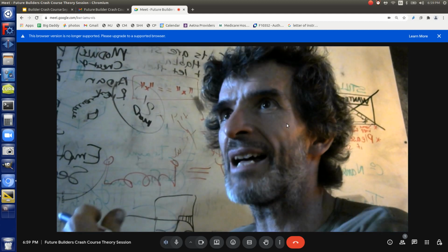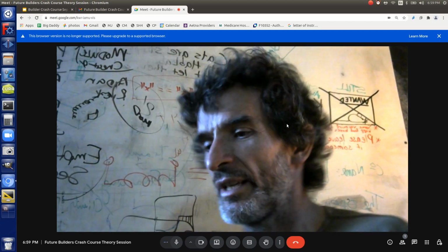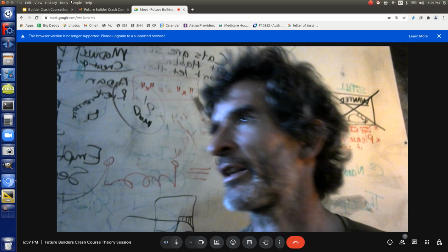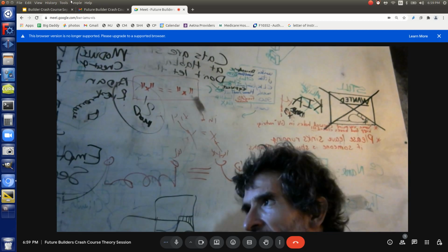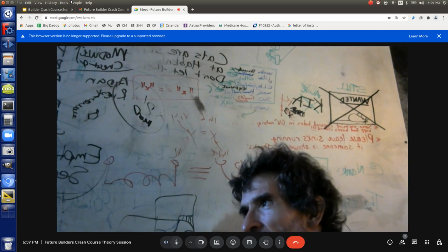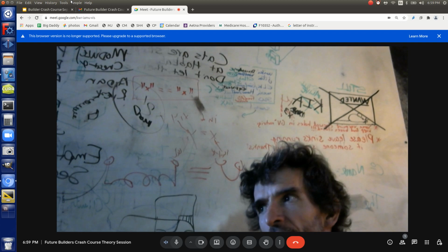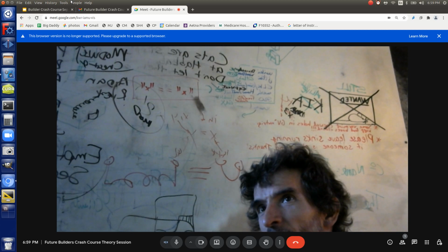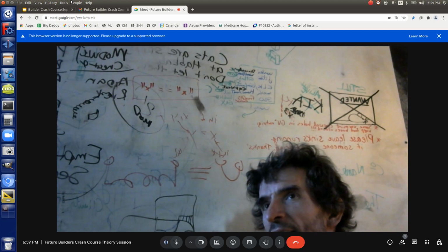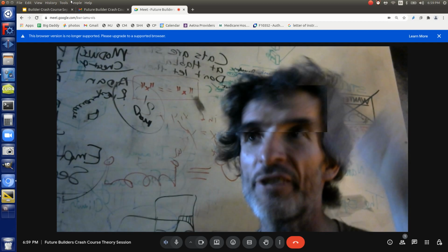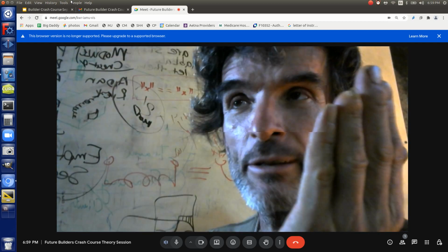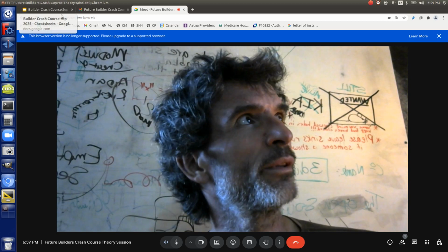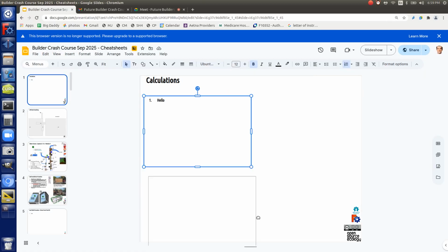And the way to think about that is in a force diagram. This is a practical thing, because you're going to ask, okay, this wall didn't exactly end up being plumb. Say it's way off, like an inch or two, and you ask yourself, is that acceptable? What else is going on here? You have to analyze the whole situation. Is it just that one little wall section that's 2 feet out, or is the whole wall out? So let's take a look at that as a practical example of force.